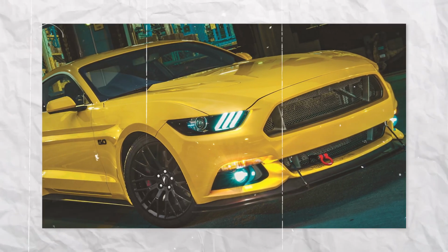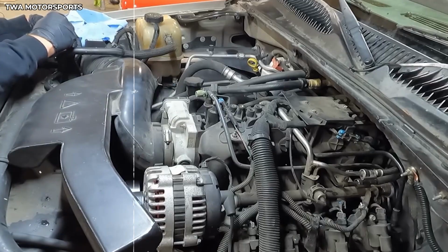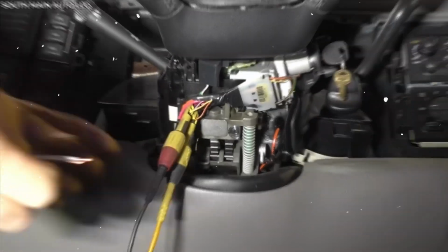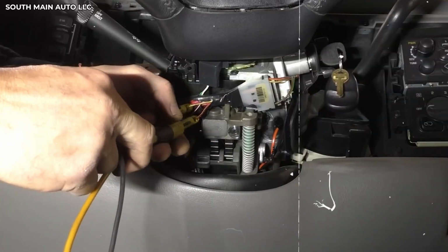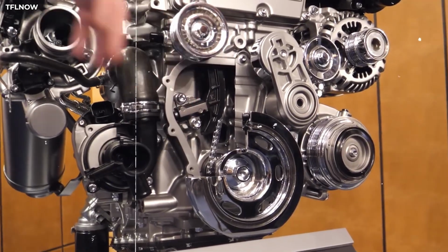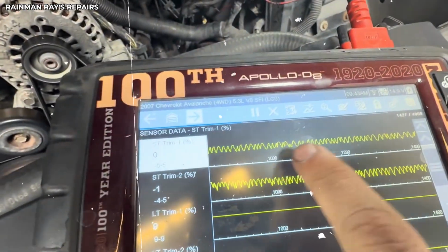Another example involved a 2017 Mustang GT with the 5.0 Coyote. The owner bought it used with 70,000 miles from an elderly gentleman who apparently never revved the engine past 3,000 RPM. The new owner was a Mustang enthusiast who wanted to enjoy the car's performance, but the throttle felt numb and unresponsive. We did a complete battery disconnect reset and thorough relearn drive.